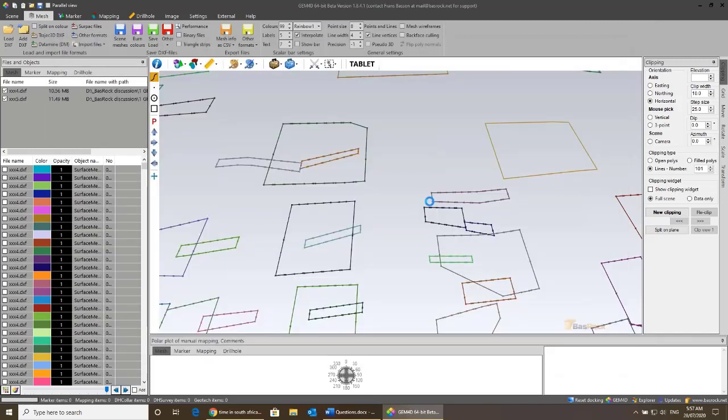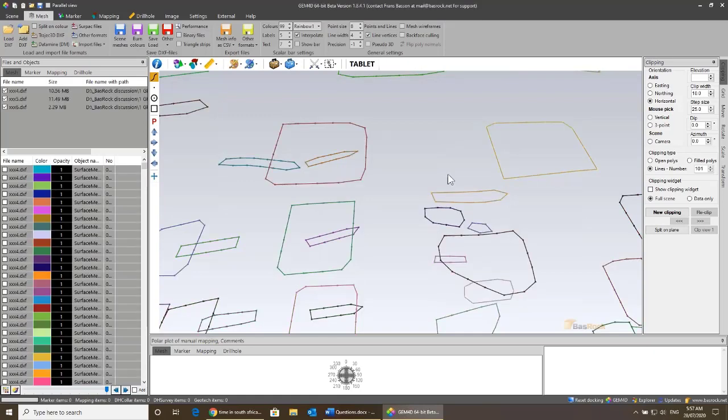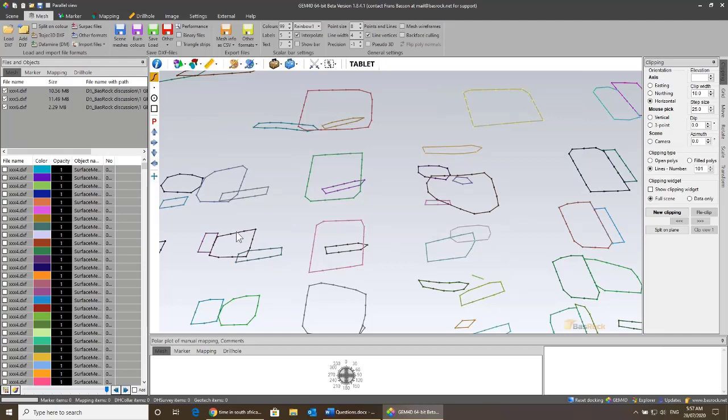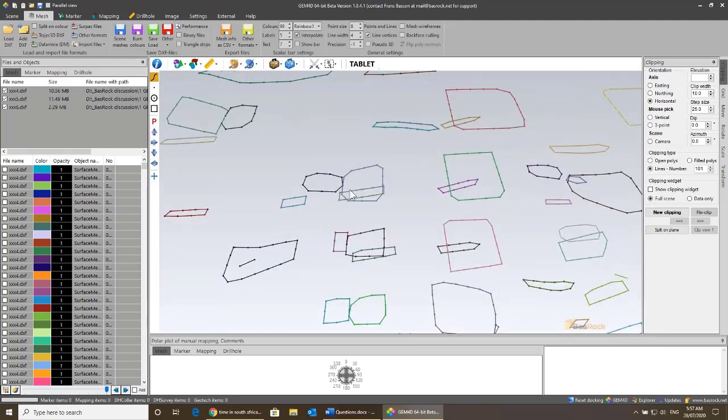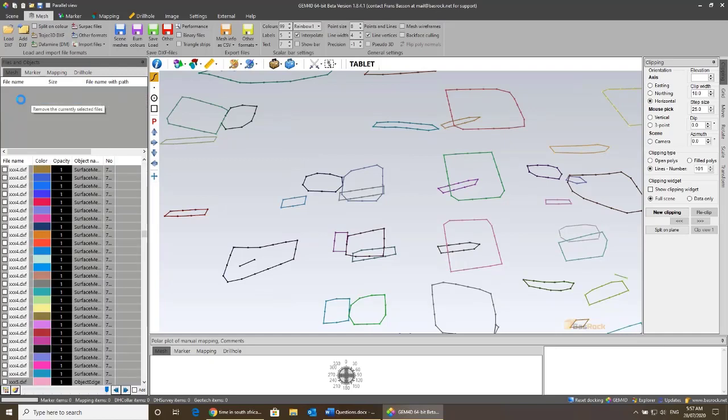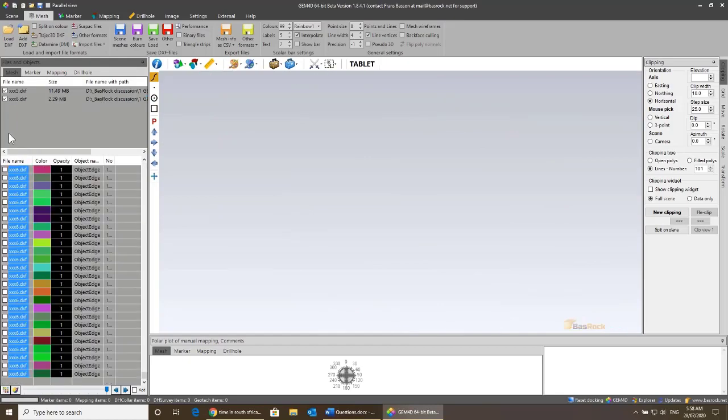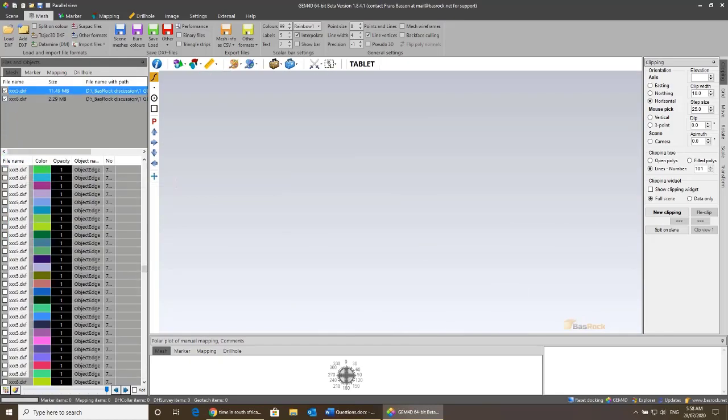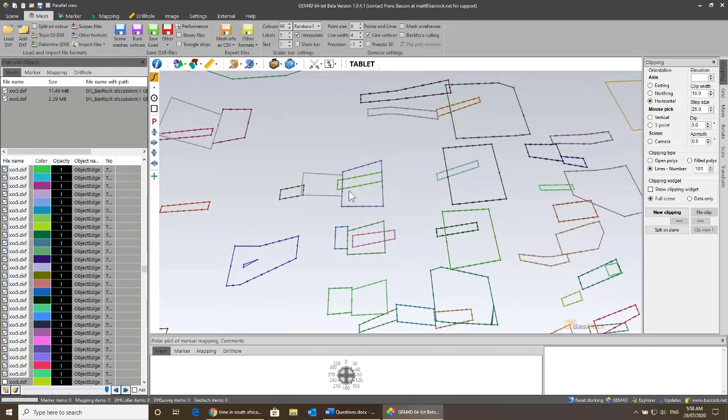And you'll see what now happens is every one of these blocks is going to have points that are an equal distance apart from one another. But some of the stope shapes have slightly changed. So if you don't like the change in the stope shapes, let's just go back to the previous file. Let's hide this one for the moment and then just unhide the previous one. Because you lose some of the definition, you can actually decide to make the distance between the points smaller. I haven't done it, so I just use a reasonably coarse value, and I'm going to continue using it.